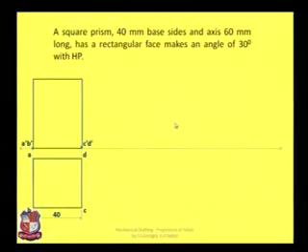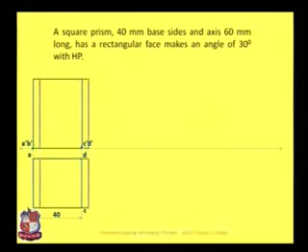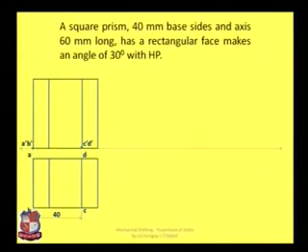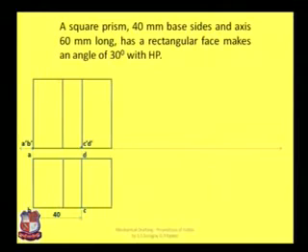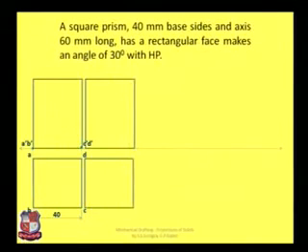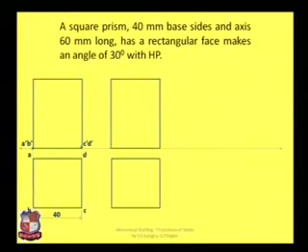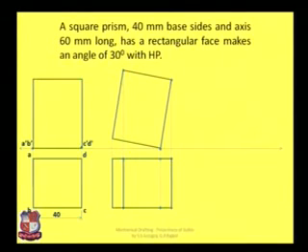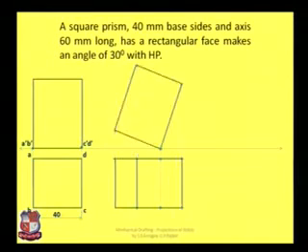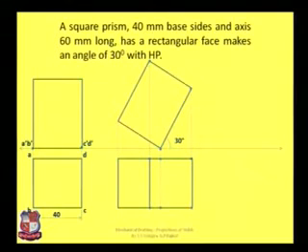First we have drawn the first view, then move this front view like this. This is the front view. As the front view moves, its top view also moves, or in other words, redraw these two views like this. Now this front view makes an angle of 30 degrees with the horizontal plane. So tilt this front view such that it makes an angle of 30 degrees with the XY line.